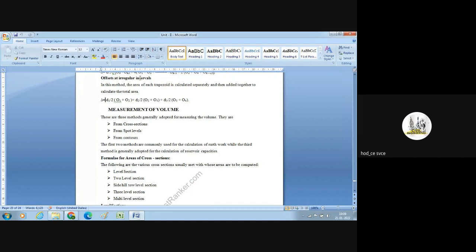There is a meridian. Next, coming to the BC line. Already you know the distance from the meridian to the point B, that is M1. Next, the BC departure horizontal distance is D2. Now you have to look at the midpoint of the line BC.